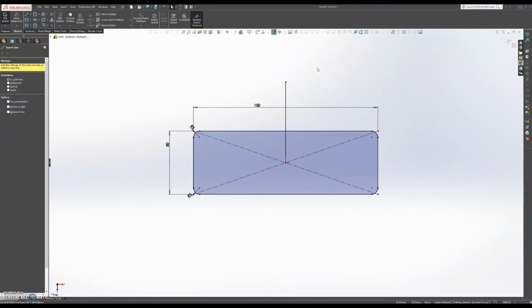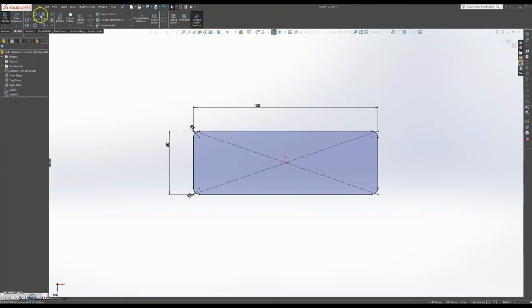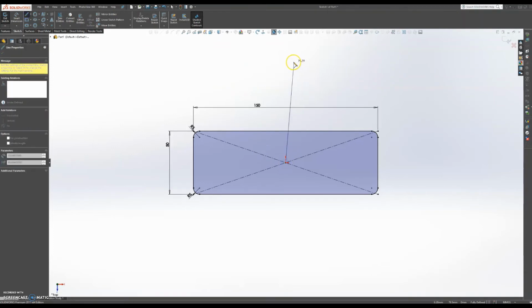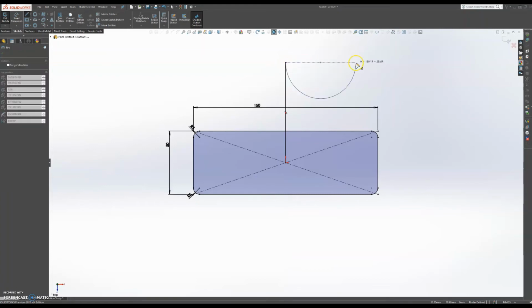But there's another way of doing that. Press OK to that, Ctrl Z to go out of it, and then you snap to the center line, you bring it up. One of the best ways to do it, instead of going back to the point and double clicking it, is to press escape.